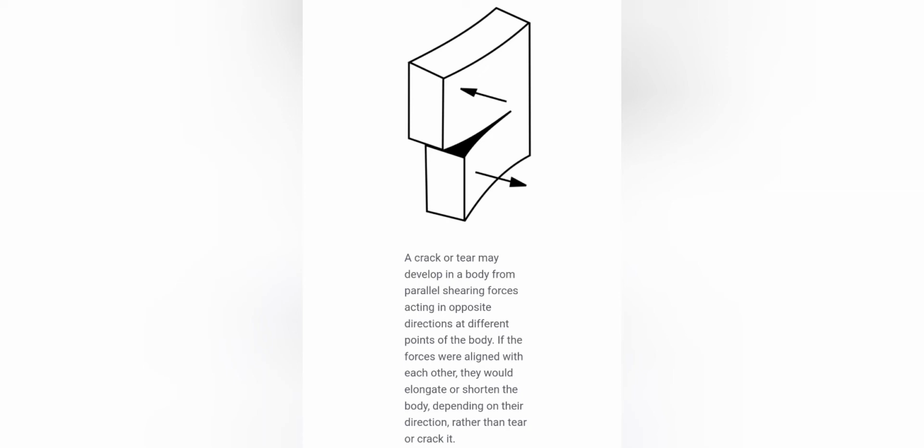Now let's see how shear forces are acting on a retaining wall. The retained soil behind the wall will try to slide the wall along it. The frictional force generated between the wall bottom and ground below will resist it, hence saving it from sliding. But if the length of the wall footing is not enough, the wall will fail in sliding.